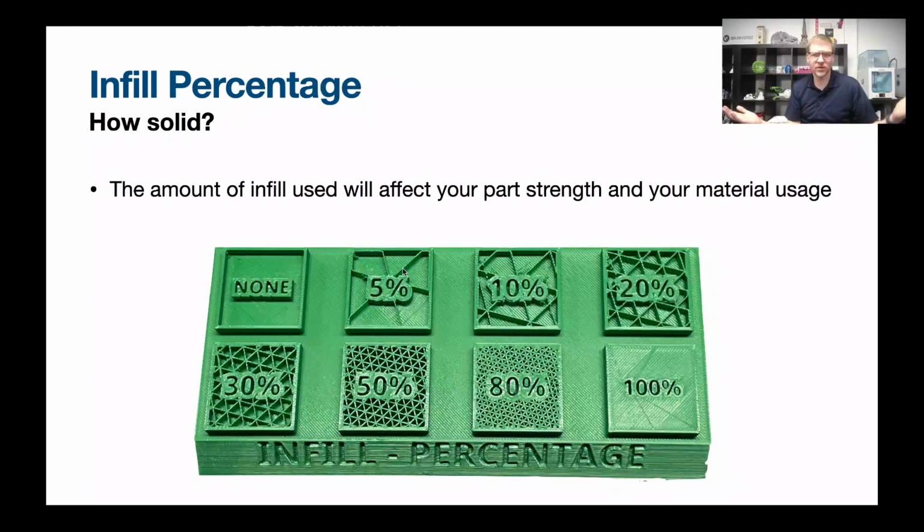Infill percentage. How much infill should I use? Well, how strong do you want your part to be? How solid do you want your part to be? If it's something that's going to sit on a shelf and people are just going to look at it, then you really don't need much at all. The infill is really just there to make it easier to print, so that you have something that's holding up the walls and makes it easier for the printer to do its job. You can get away with 5%, 10% infill.